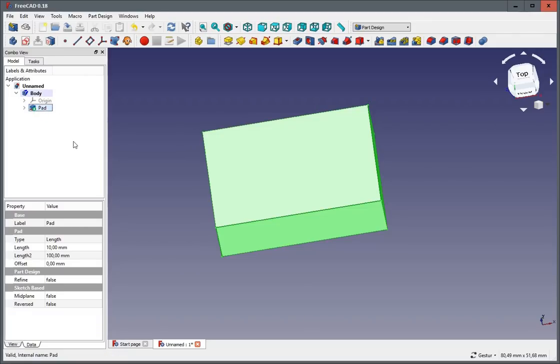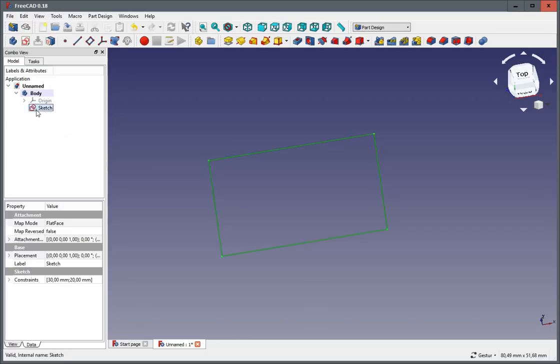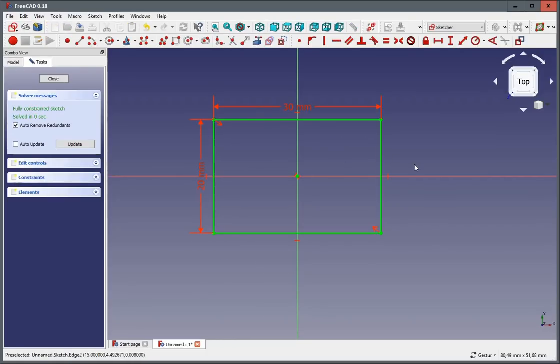We want to do it on the level of the sketch, because we might want to construct something that will be, let's say, tangent to one of the fillets, and you should not create a tangent to a fillet that was made on the feature level, because you know they can easily change their naming and you will run into trouble. So if you want to construct something that uses fillets, which you're gonna reference later, better do it on the sketch level. So normally that's quite easy.